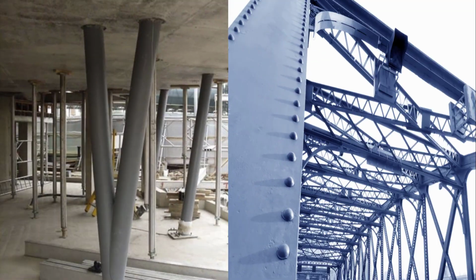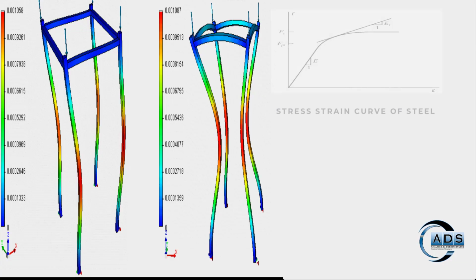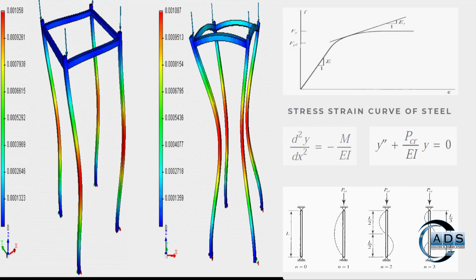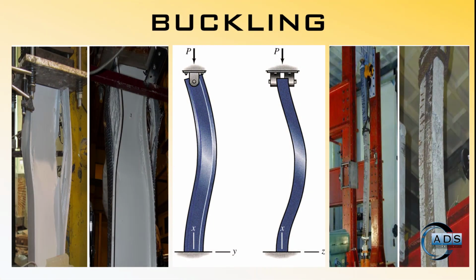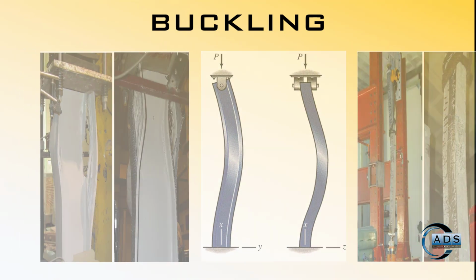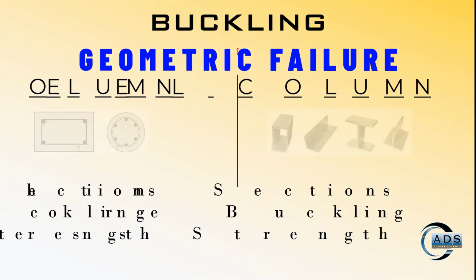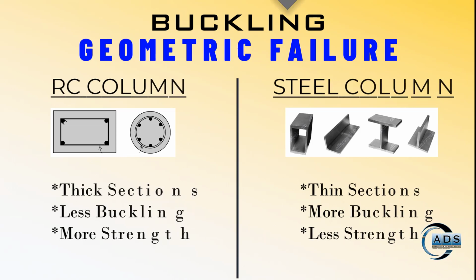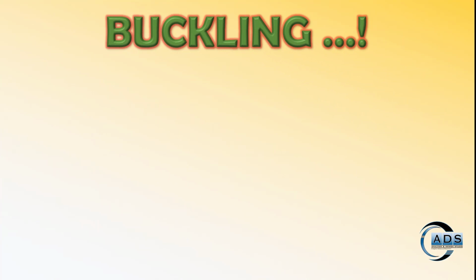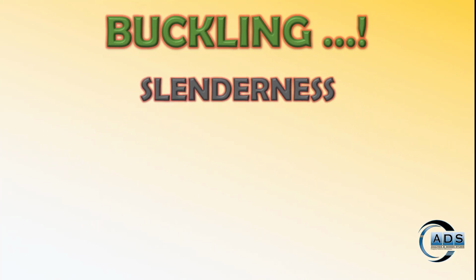While designing the columns, there are many factors on which the column strength depends. One of the main factors is buckling. It is the geometric failure for columns. Steel columns are geometrically having thin sections compared to reinforced concrete columns, so they are more prone to buckle. While considering buckling, the term slenderness comes into the picture.